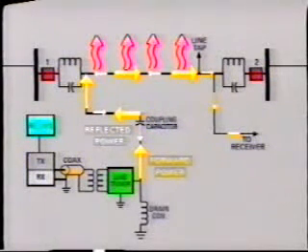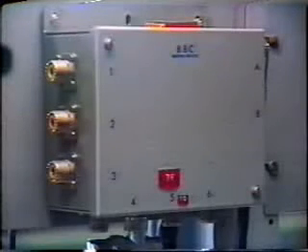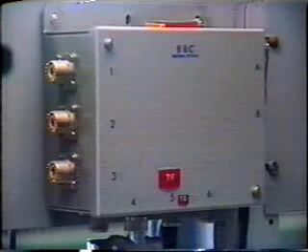In our power line carrier system, we do not want any portion of the signal to resonate and give off energy. If this should happen, the energy would be radiated and therefore lost into space, instead of being transferred down the transmission line. In order to prevent this loss, it is important that impedance mismatch be reduced as much as possible.